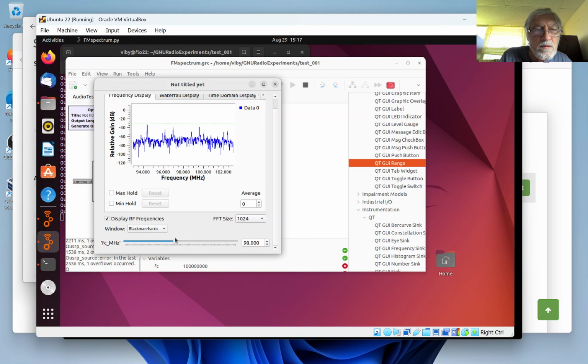So if you go a little bit further down in the FM band, you can see some of those. So there's a station, for example, here at about 94.6 megahertz. We can increase the average so that we get to see less noise and more peak, like this. So now you can see that there is actually some signal somewhere out there. If we really wanted to listen to those signals, then of course we would have to build a receiver.